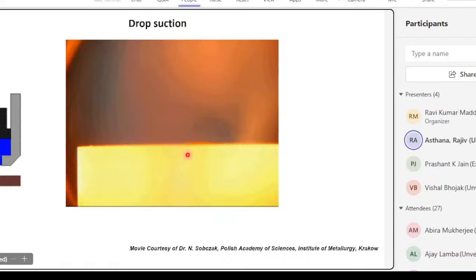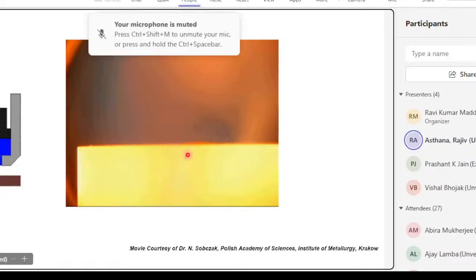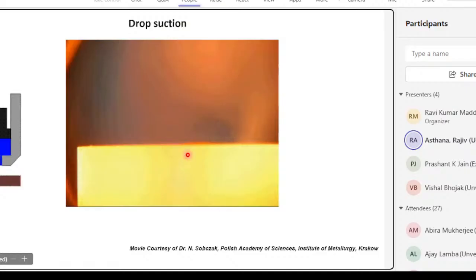Metal shrinkage during solidification. You see the liquid is in contact with this single crystal plate here. When it is cooling, the shrinkage will cause this plate to be lifted up, because good spreading, good wetting means there is good bonding, and therefore this plate will be lifted up.